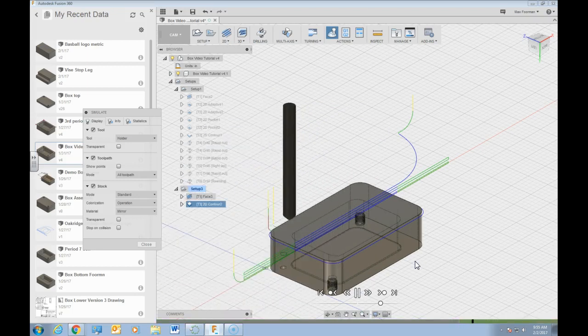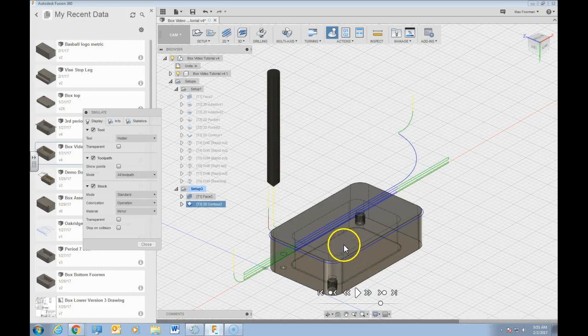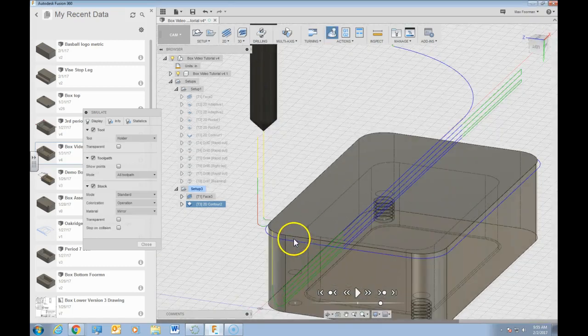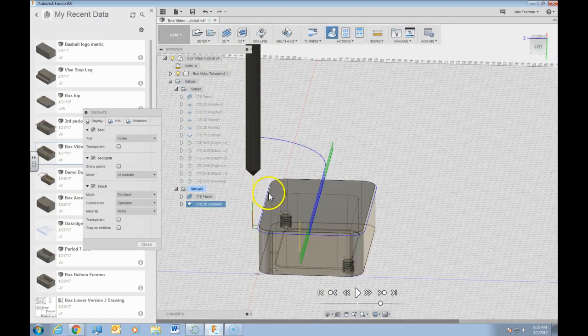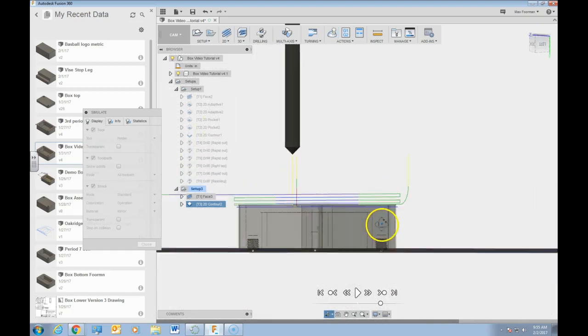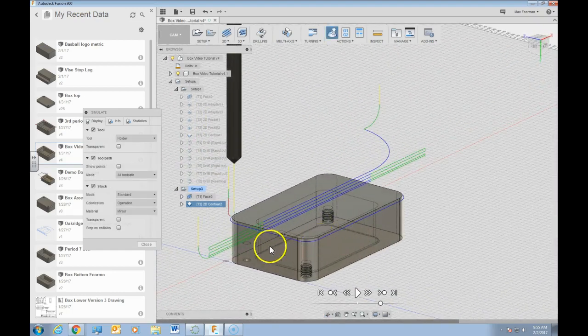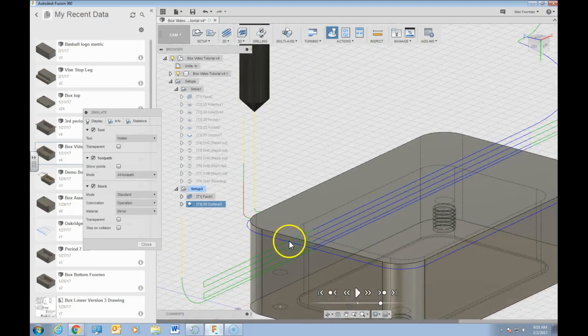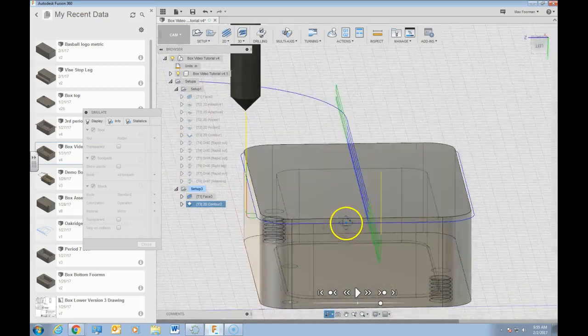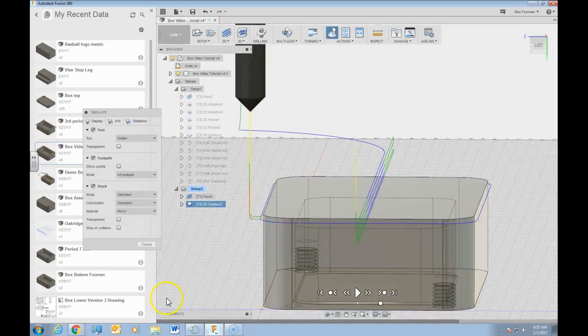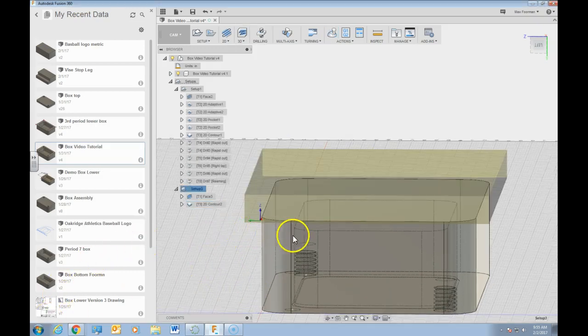Through, remove that material away. Now we're using our chamfer mill to come in here. Now in the simulation, it's not doing the best job of actually showing what material was removed away here. We would actually have to drop the stock level down a little bit, which is also going to be a little bit touchy. So note to Fusion 360 developers, if you can figure out how to generate a stock from previous operation function that's more accurate to this whole setup and then include that, that would be an awesome feature. But they're probably working on it at some point, have probably higher priorities at this point.